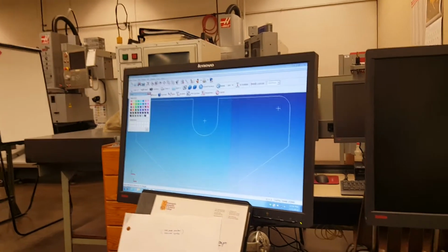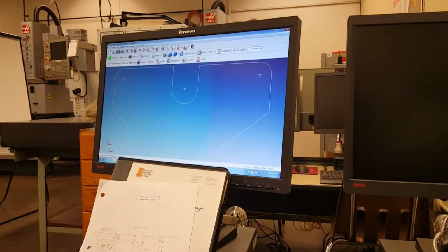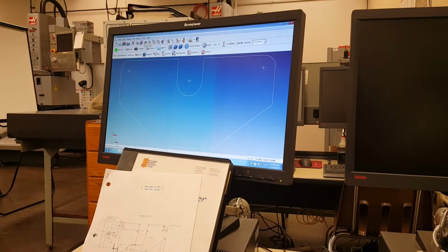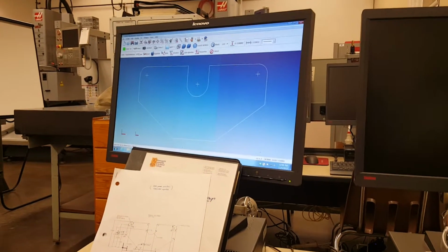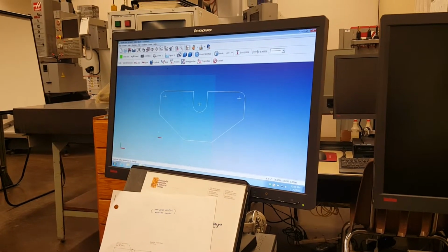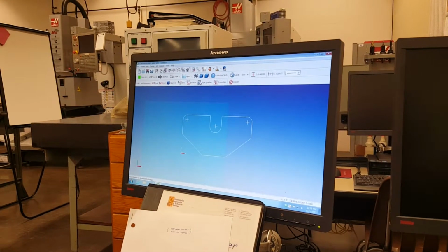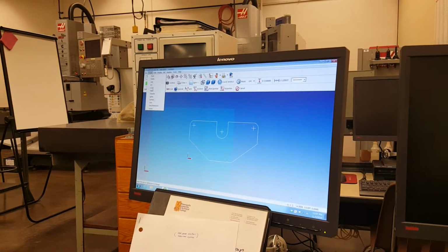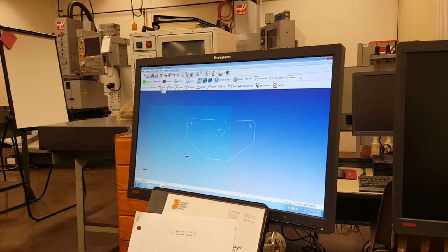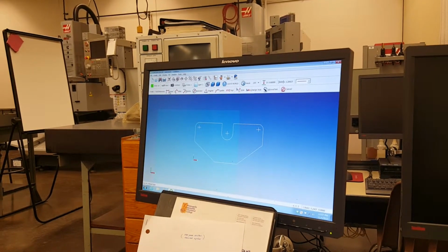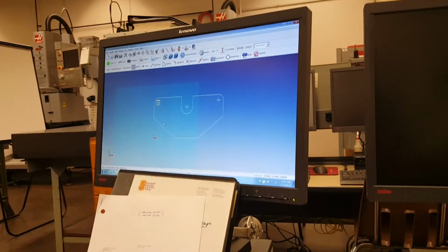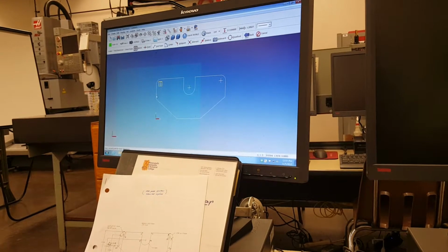Now I'll change my color. And let's just change it to green. It really doesn't matter. Then I'm going to zoom out, right there, and make my part smaller. I'm clicking it over and over again. Okay. Now I can go create, text or dimension, linear, and I'll go from this point to the end point of this line.